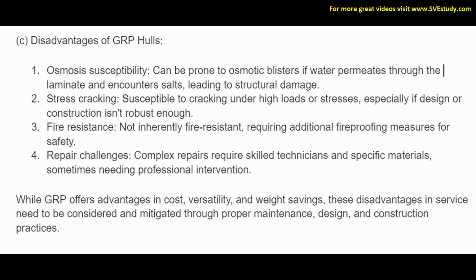C. Disadvantages of GRP hulls. 1. Osmosis susceptibility. Can be prone to osmotic blisters if water permeates through the laminate and encounters salts, leading to structural damage. 2. Stress cracking. Susceptible to cracking under high loads or stress, especially if design or construction isn't robust enough.